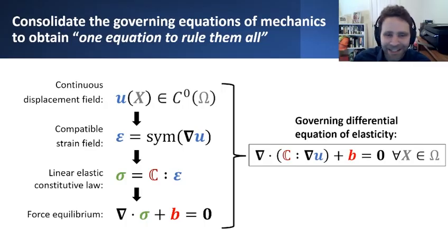And we could combine that further with the force equilibrium equation to finally come up with one governing equation to rule them all, if you like, expressed solely in terms of the displacement field, which serves as the primary unknown we're looking for. If we find the displacement field, then we know everything else.